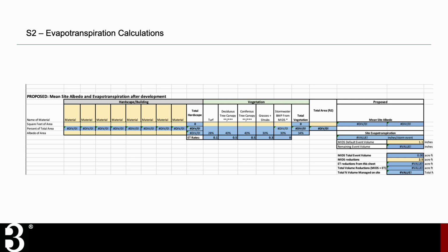In a non-evapotranspiration focus sense, we've also simplified the amount and complexity of materials that are available to input for hardscape albedo in this tool. So we've simplified the options, simplified the list, and arranged it, really going pretty linearly from low albedo to high albedo. So the team should choose the best material to suit your project's needs, and these values go in the bottom row of the calculator, yellow there, that is set up for an input.